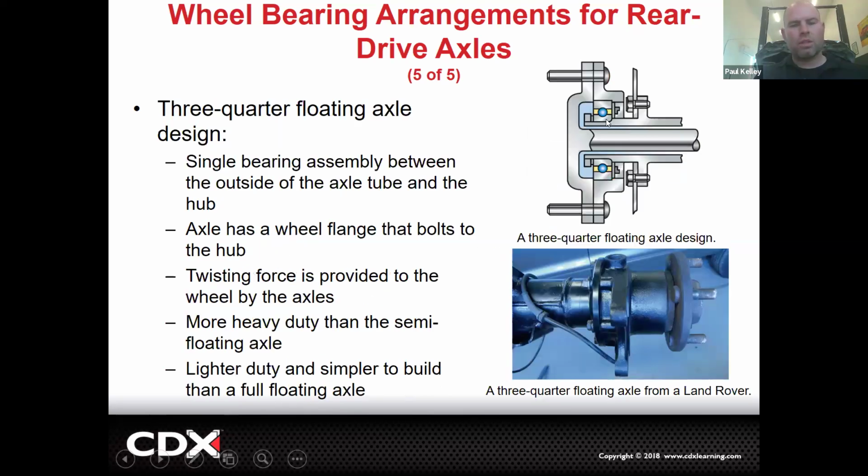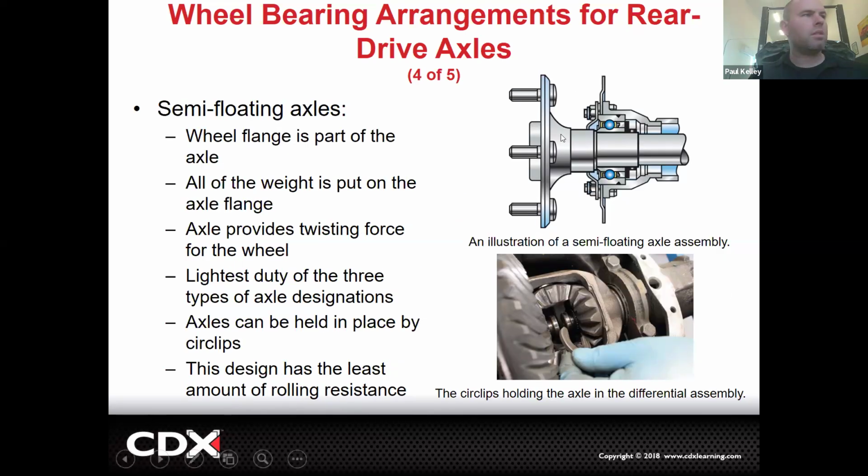Let's jump real quick to this one. Actually, no, I'm straight now. This axle is literally just sitting on that bearing. So if you put a whole bunch of weight on it, that's going to push all the weight down like this, and this bearing is literally sitting on the axle shaft. That's very hard because the tire is sitting on the hub, and so the tire is holding it, but the axle shaft is trying to go down, putting a lot of stress in that axle. See how that's a negative.